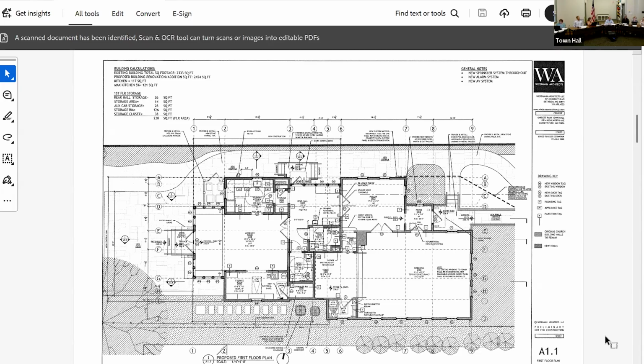I was in the fire department many, many years ago, and we always had systems that were both. We had a smaller water main that came in, and then there was a flapper valve, and then the fire department could hook up when they got there, which would close the flapper valve and allow the pumper to pump water into the system for additional flow. But in the time it took for the alarm to go off and the fire department to arrive, the smaller main was what actually fed the sprinkler heads. Okay, I will investigate further. Thanks.